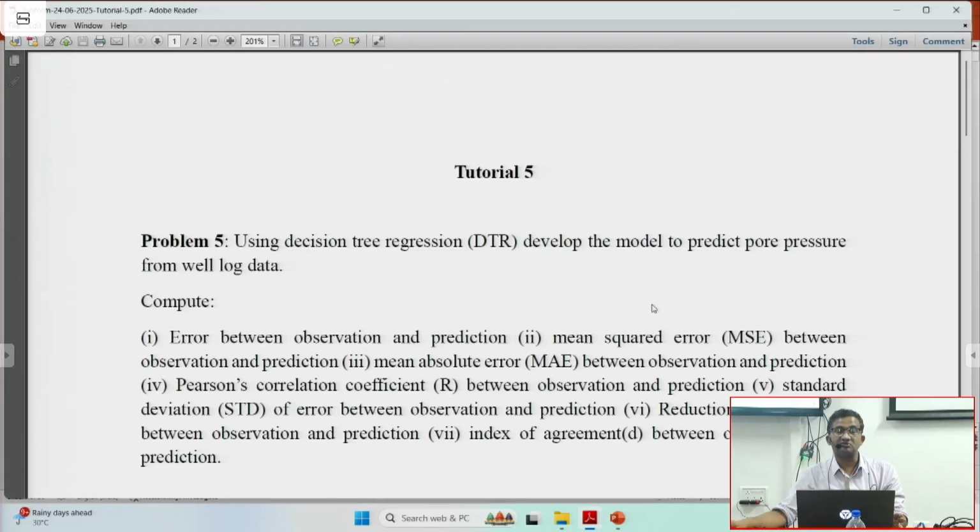What is important is that this pore pressure information will be used to avoid blowouts. It is a hazardous phenomenon in the oil industry. Once a blowout happens, that means the formation oil pressure is very high, higher than the drilling mud, the fluid we inject to make that balance. Once it is high, all oil and gas will be expelled, and there will be high chances of fire, and the whole area has to be evacuated. This type of hazard is very severe.